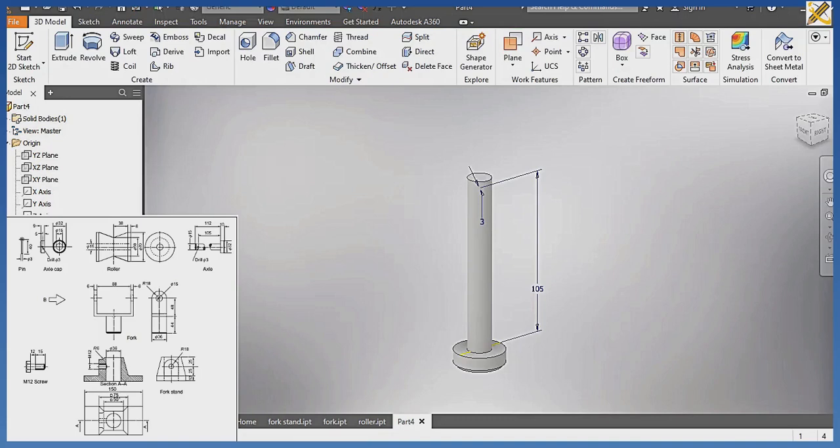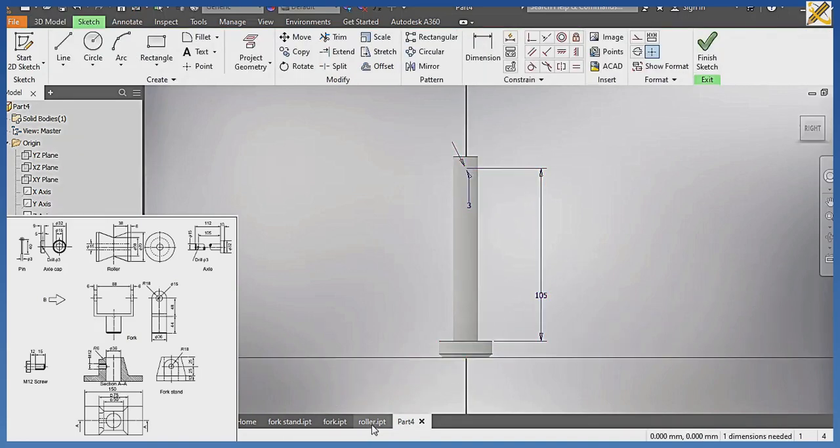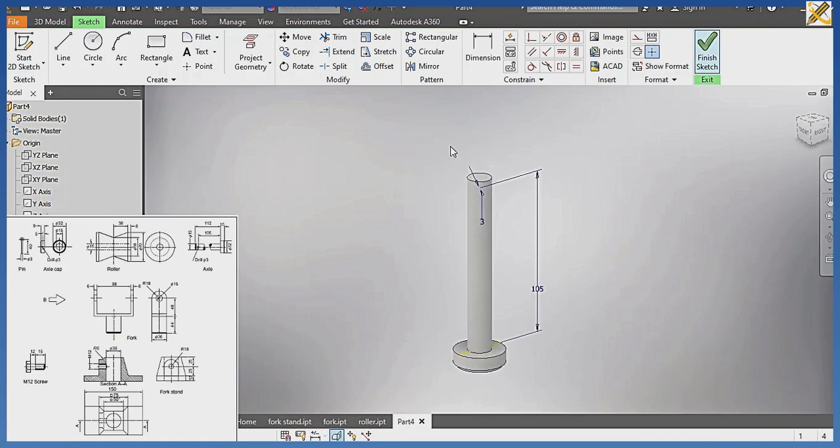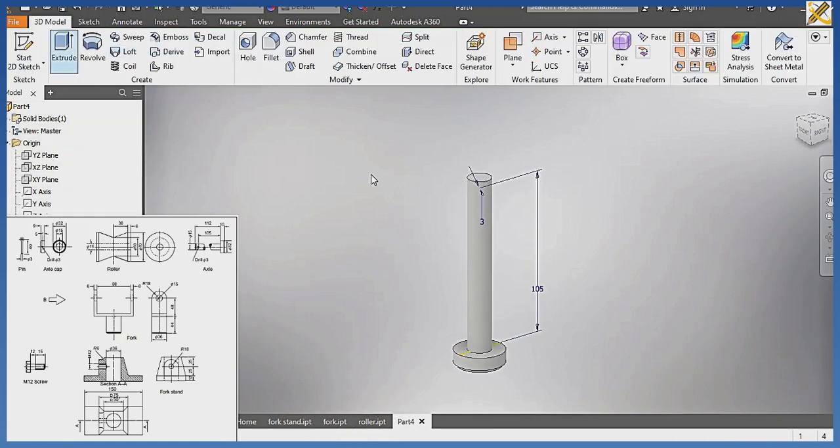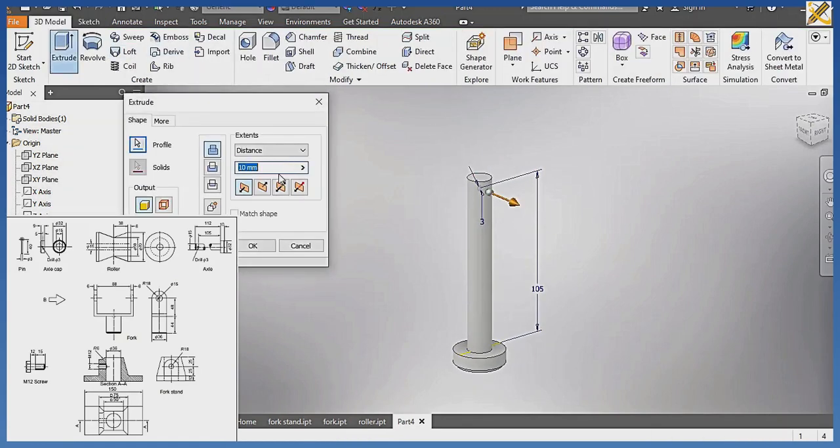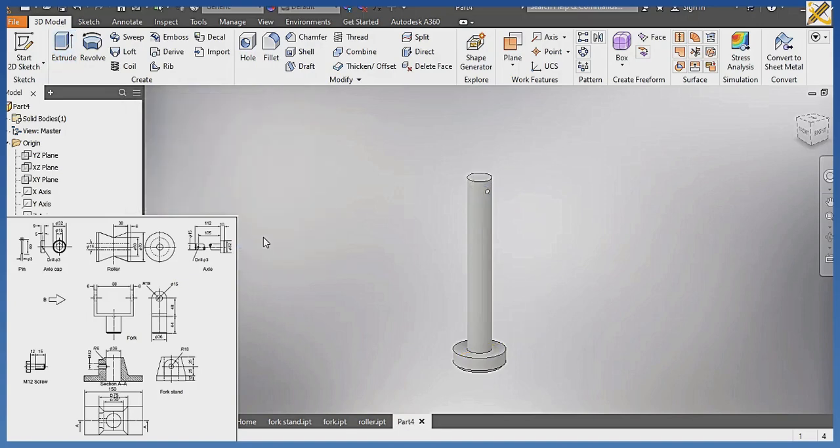Do you see that? So then coming to my sketch 2, double clicking on it. Okay, clicking on my slice graphics. So I have this already positioned. Then what? Finish sketch. Finishing my sketch, I pick what? Extrude. With my extrude already picked, I pick distance, symmetric. Then I pick what? All. Then I pick what? Cut. Okay, then I click on what? Okay. In that order.